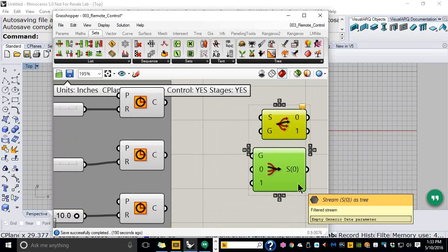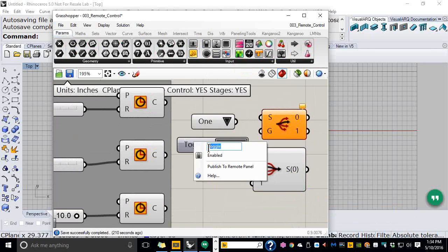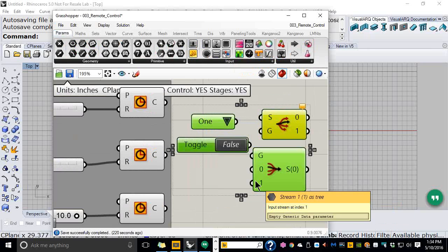So sometimes, whenever I want to do Boolean operations, it's up to me. I choose whenever Rhino and Grasshopper are going to do those Boolean operations. So I use a lot the value list or even the Boolean toggle. And I say, unroll, do not unroll, things like that to make Grasshopper run a little bit faster.